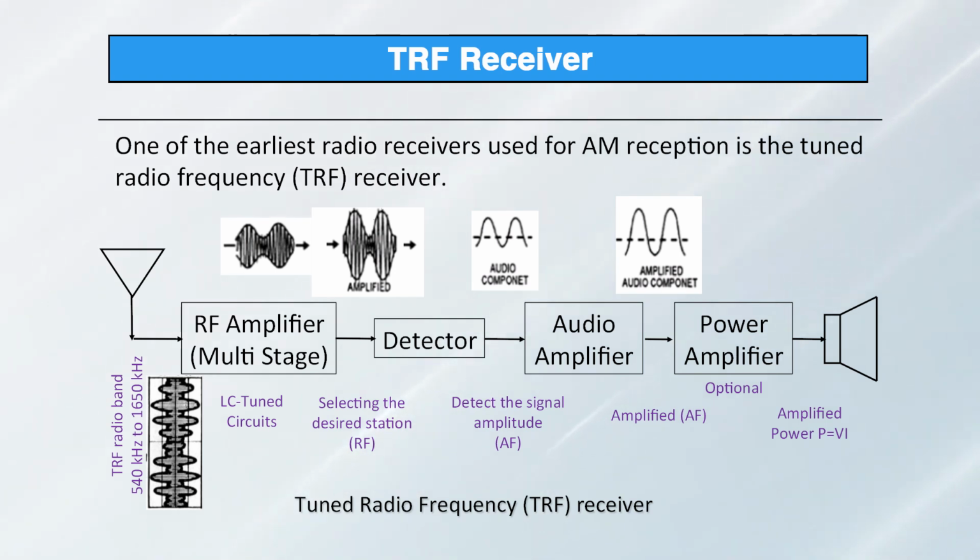It may consist of one or more stages of amplification to achieve the desired output level. Signal fidelity and low distortion are critical to ensure accurate reproduction of the audio signal. Impedance matching with the output transducer, speaker or headphone, is essential for effective power transfer.